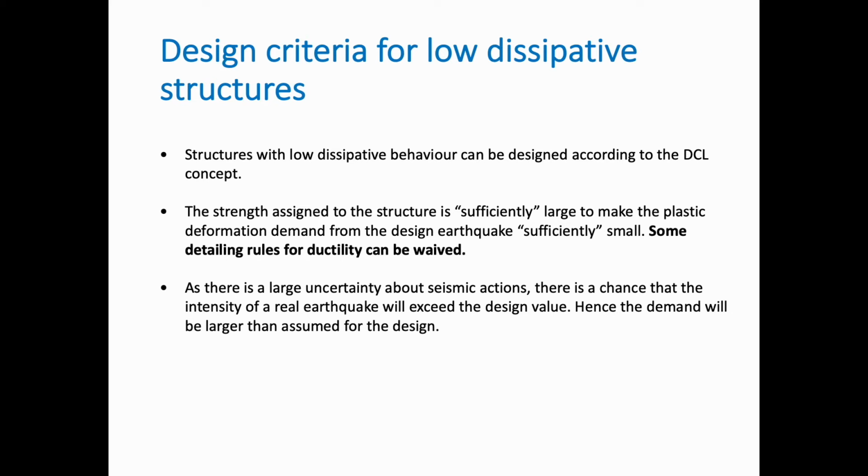There is a large uncertainty about the seismic actions, and there is a chance that the intensity of a real earthquake will exceed the design value in such cases. Hence, the demand will be larger than assumed for the design. In other words, we will over-design the structure, we will provide more strength to the structure to account for the uncertainty of larger seismic actions onto that structure.